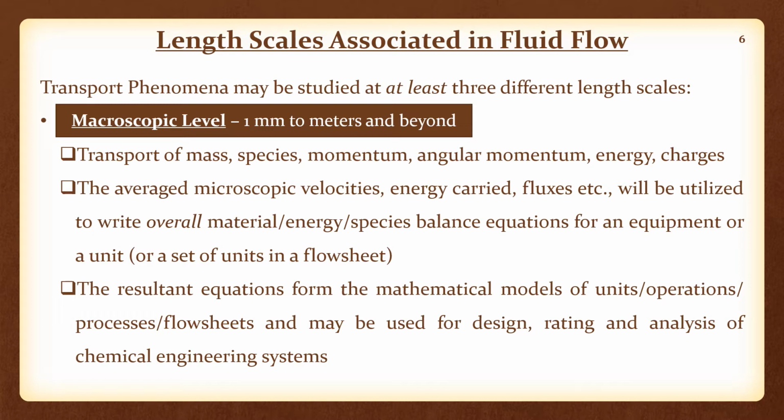So you are not per se interested in the spatial variations of, for example, velocities in a reactor or in a plug flow reactor. That's why you call it a plug flow reactor, right? You neglect the spatial variations, at least in the cross section, and also of course at steady state along the length, or in a tank, or for example on a distillation equilibrium tray tower, right? An equilibrium stage in a distillation column.